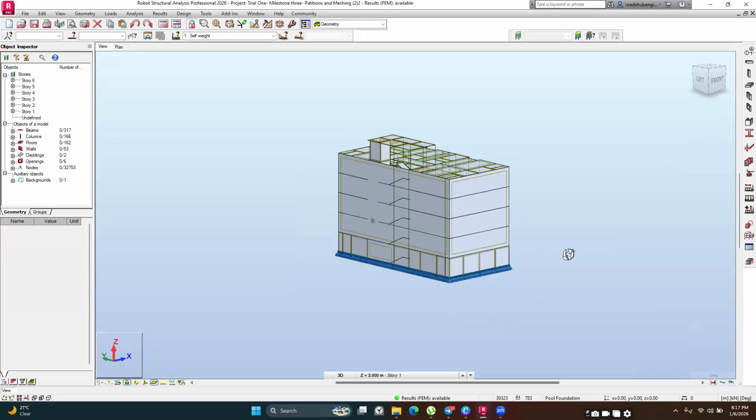So basically, at this point, we've all understood what we have done. We started with the architectural floor plan. And then from the architectural floor plan, we were able to decide where we want most of our structural members to be, right? So we got to choose where we want our columns to be, where we want our beams to be, the types of slabs we want, their depth. We got to make preliminary sizes, and then you also got to model the other members, such as the staircase and the ramp, right? Then after we model them, we got to load them and create the combinations.